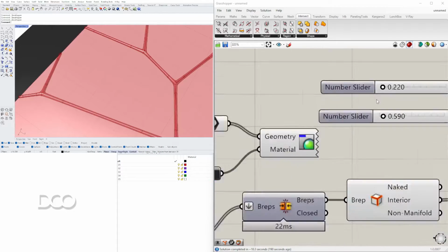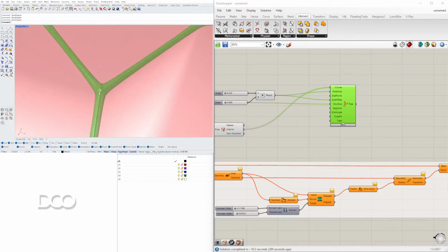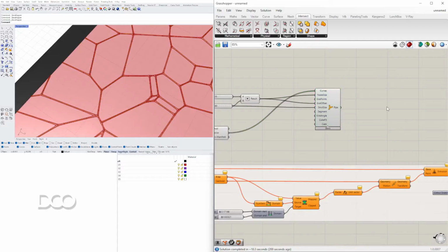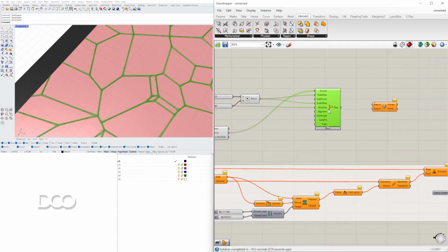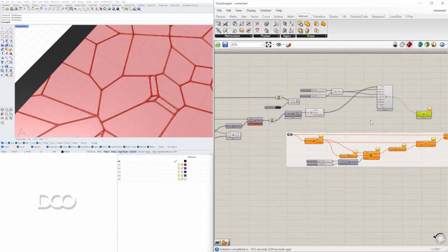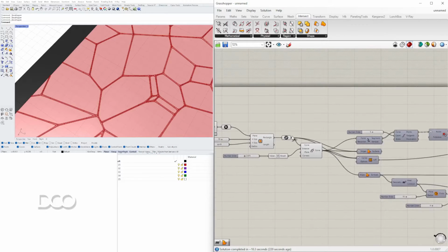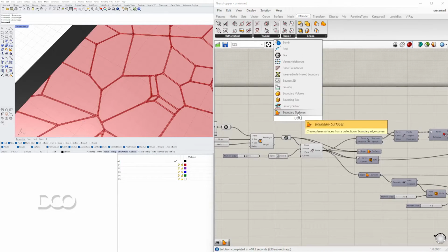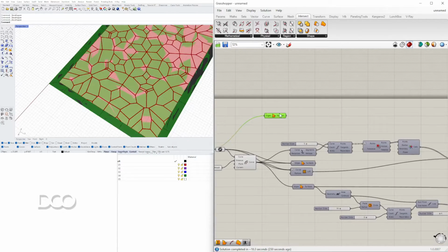Now that we have this entire sub D pipe, and it's all one because we only have one line segment, and it creates it really clean here, we're going to go to intersect brep with brep. So this pipe, the sub D pipe, is going to go into this brep. Now it's not a brep, it's a sub D, so that might give us an issue, but here at the end, I'll go to boundary surfaces just for the outside surface and intersect it with that.